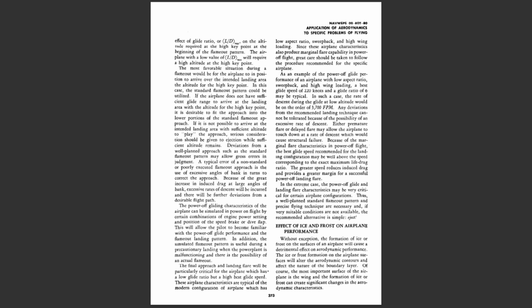Any deviations from the recommended landing technique cannot be tolerated because of the possibility of an excessive rate of descent. Either premature flare or delayed flare may allow the airplane to touch down at a rate of descent which would cause structural failure.